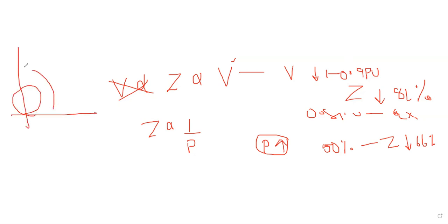So we have the Mho characteristics like this. This is zone 1, zone 2, zone 3. Suppose my load point is here, maybe due to load encroachment or power swings. Power swing is similar to this. Maybe when you are generating, the generator should always be synchronized with the grid straight away. If there is any issue in stability as per the equal area criteria, that may lead to this, or these load encroachments may lead to the load point falling under this zone.